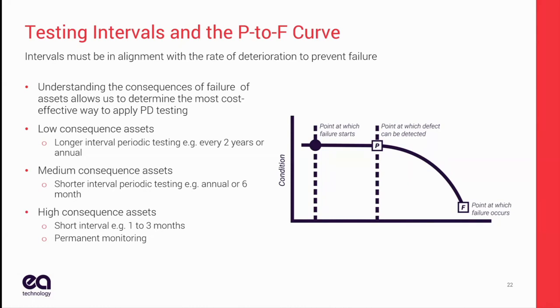What we can do is look at detecting or doing surveys more frequently on critical assets. If you've got something that's feeding your factory, and if that cable goes down, your factory goes down, well, you really want to look at that pretty often, and even more often if you're starting to detect a low level. You might even want to put in permanent monitoring if you have a few critical non-redundant cables.